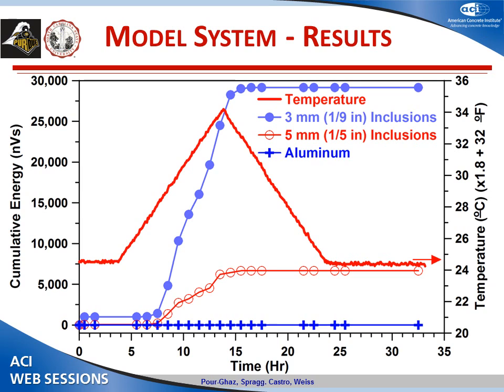The first thing that I want to take away from this is that we can see some acoustic activity regardless of the aggregate size after some increase in temperature. For example, if I go back here, approximately after a 4 degrees C temperature change, we can listen to the sound of cracking. The other thing that I want to take away from this is that I do not hear anything on the aluminum. What we are trying to show here is that there is no cracking inside that, but the objective is to show that there is no change in the properties of the coupling agent.